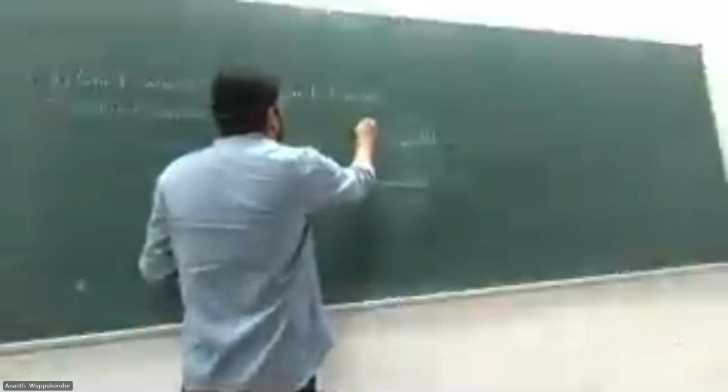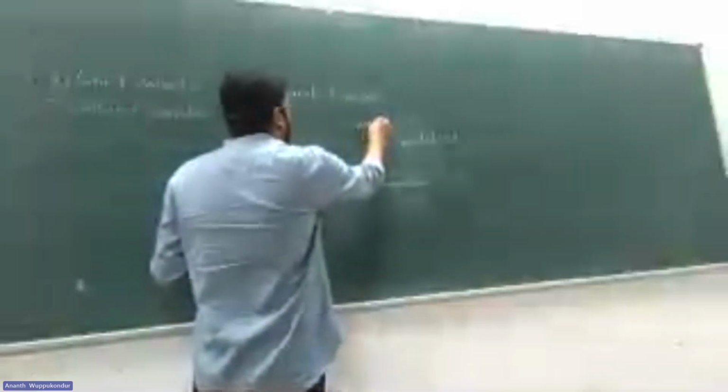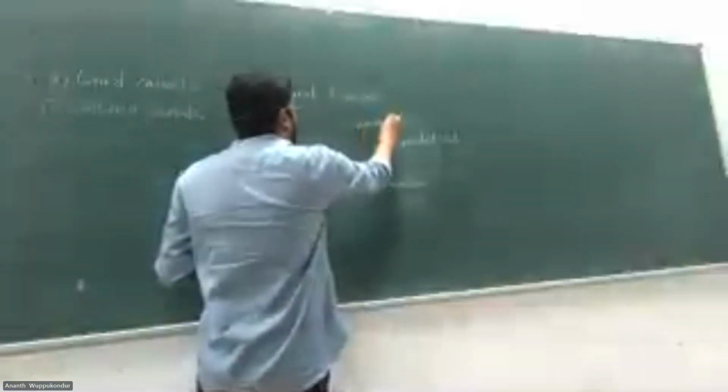And then if there are particles much finer, they would be traveling as wash load. So generally we can quantify bed load and suspended load, but wash load is very difficult to quantify because they are very fine particles. So these are the three different mechanisms of transport for the sediments.